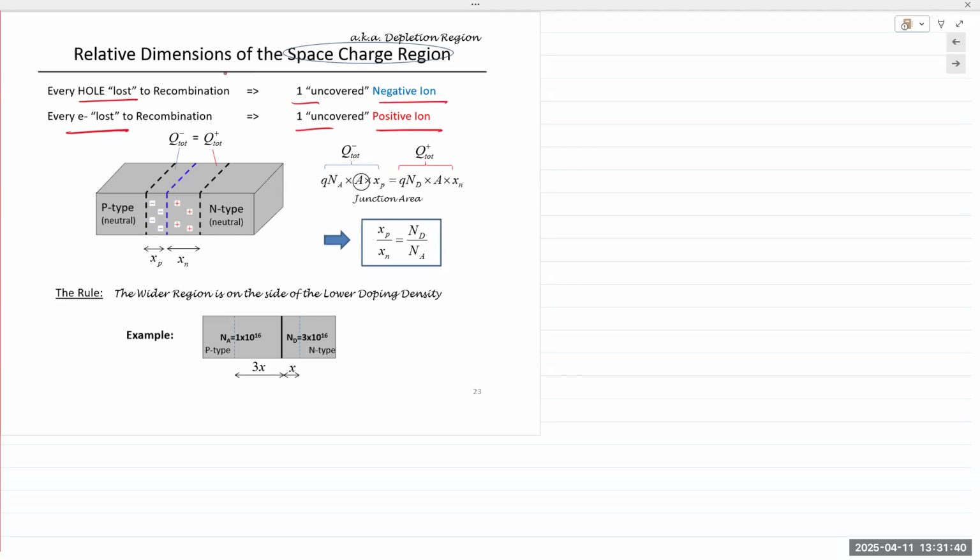electrically neutral PN material. In order for that to occur, if you have a concentration of electrons that is higher on the N side and a concentration of holes that is lower on the P side, for both sides of the depletion region to be electrically balanced, meaning the charge density should be the same, the only way that can happen is if charges are higher on this side, the area would be smaller. And if charges are lower on the P side, then the area would be bigger. That's the only way the charge densities would equal and cancel out.